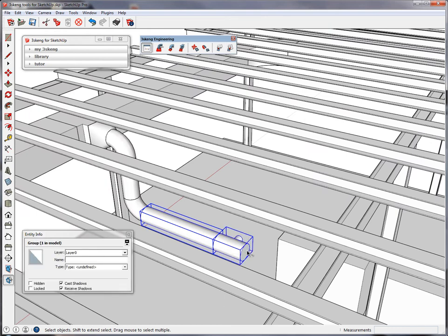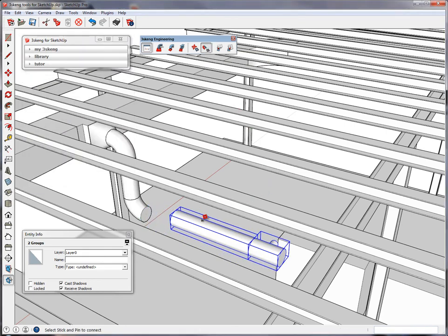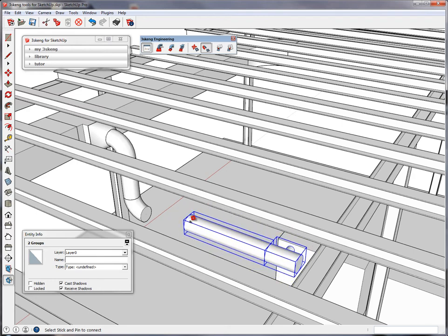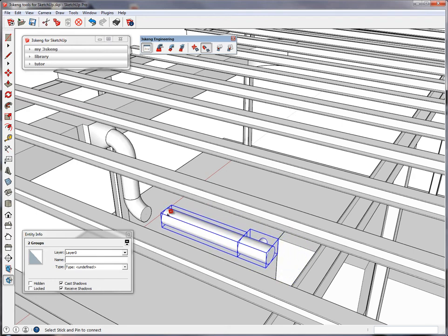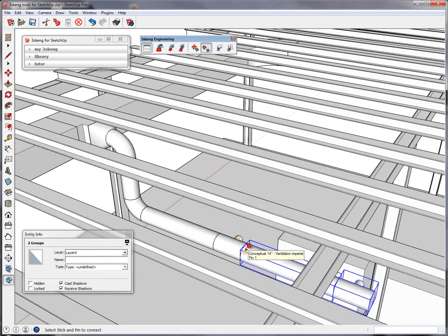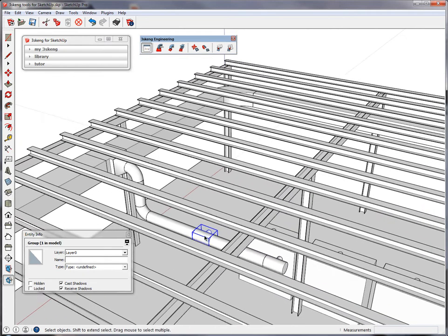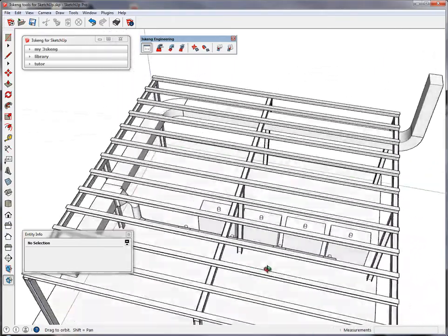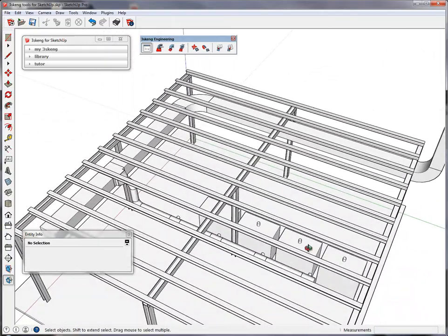We just use these two components now, mark them, and use the connect tool for the first time. A left click allows us to either move the selected parts somewhere else, or by hitting the control button, just duplicate them. Now we will duplicate these 4 parts another time in order to have an outlet for each and every one of the fume hoods.